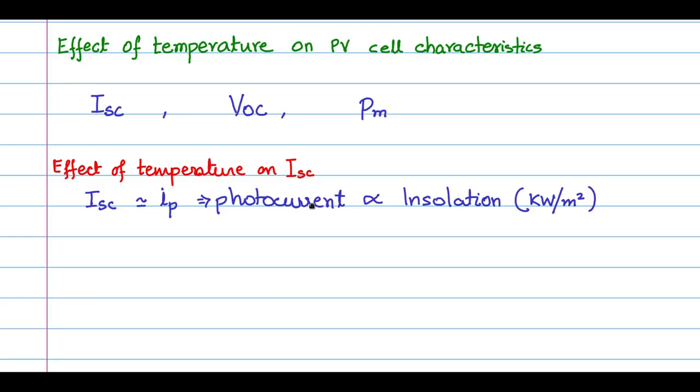The band gap energy was 1.16 electron volts, and it will come down, and this will allow more valence electrons to jump into the conduction band, and therefore there are more free electrons, and as a result more photocurrent, and therefore a higher value of ISC, short circuit current.